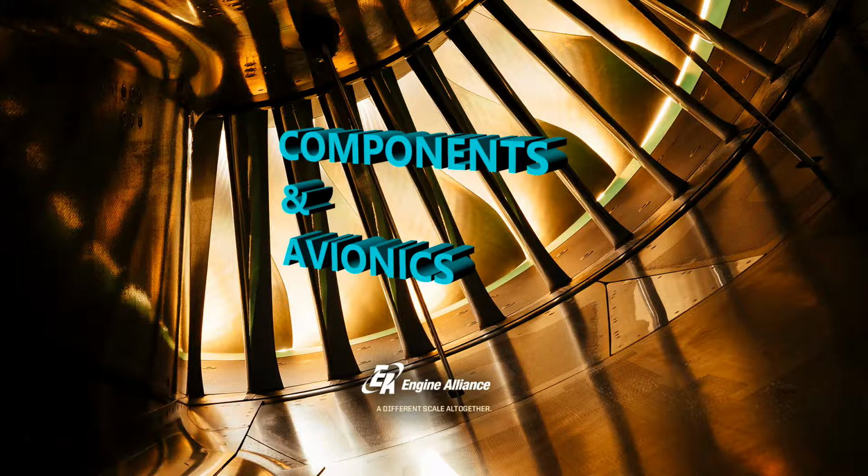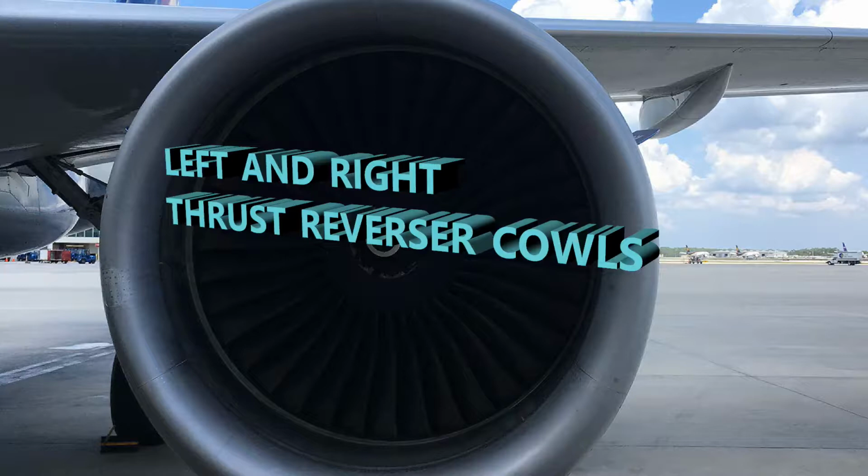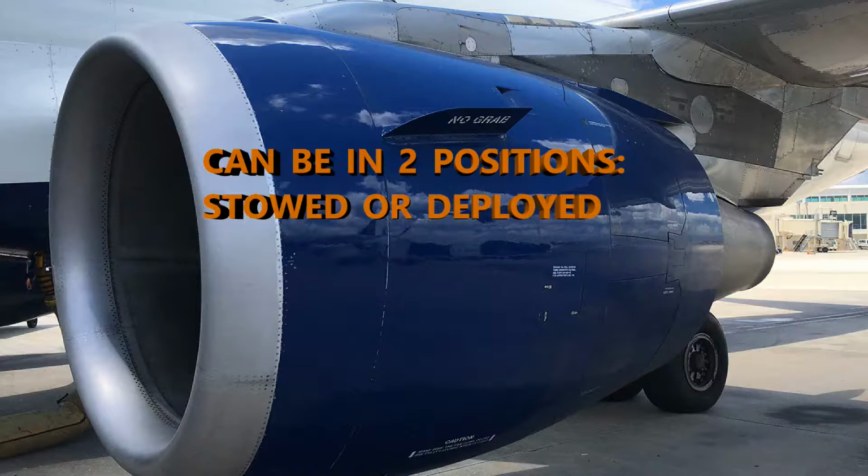A lot of avionics that we have with the thrust reverser system, just like the other systems. The thrust reverser system is obviously part of the engine, which is the Rolls-Royce Trent XWB, that is all electrically controlled and operated. We'll get into some parts that are going to be a mixture of electrical and mechanical, but when we talk about the reversers, they are electrically controlled and operated. There's a left and right side, so you have thrust reverser cowls for each engine, and a translating sleeve. Translating just means something that slides. That's going to be able to be in a stowed or deployed position given commands from the cockpit.